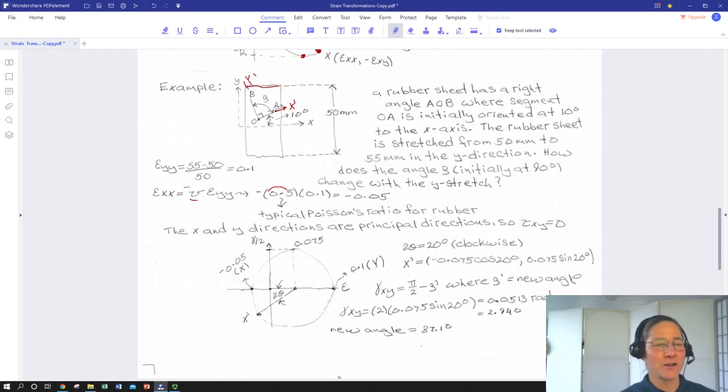And they're at a right angle, and we could define the angle beta between them, which starts out at 90 degrees, and we're interested in what's the strain that we're going to see. The shear strain, so what reduction in that angle beta? By looking at the angle beta as the angle between what's basically a rotated coordinate system, we can use our Mohr circle strain transformation to basically get the shear strain. It's going to be represented by a change in that angle beta.